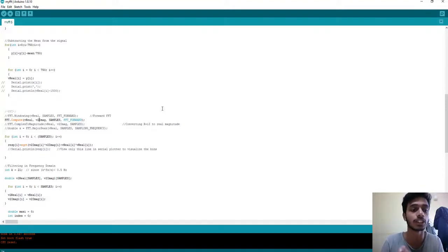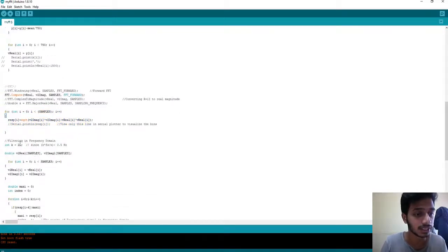You'll have the magnitude spectrum in it. You'll have the Fourier transform in it. Since I have the Fourier transform and I need the magnitude spectrum, I will be computing the magnitude spectrum here. Now I need the components of the respiratory signal, and we know that the frequency of the respiratory signal will not be higher than 0.5 hertz. So from this equation, solving this equation, I can get the value of k, which here is about 21.